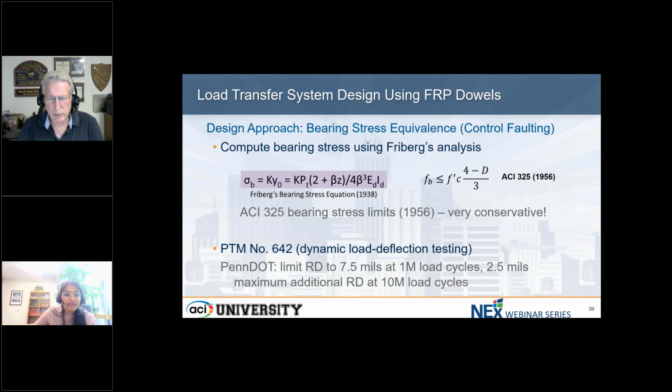Well, my impression was that there are limits on using GPR, obviously, with the moisture content of the concrete at early ages. But my understanding is that GPR and ultrasonics will see them. The densities are fairly similar, like you said, but with ground penetrating radar, you have a distinct boundary where you're going to reflect the radar between the concrete and the FRP. So I guess I'd need to talk to this person more.